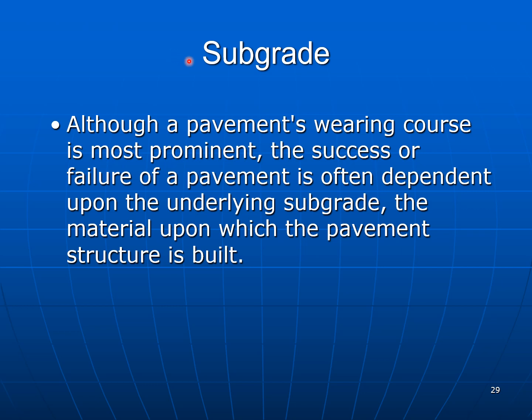And then the subgrade. Although a pavement's wearing course is most prominent, the success or failure of a pavement is often dependent upon the underlying subgrade, the material upon which the pavement structure is built. So that's why the subgrade is very, very important.